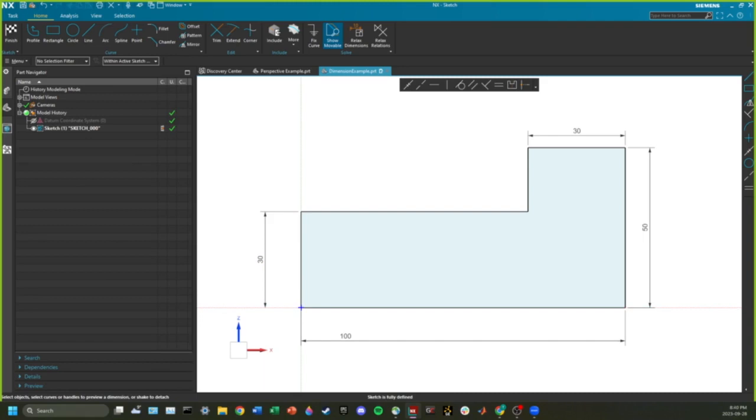In manufacturing, this is good because imagine you had one true edge or one true corner, and you know that everything from this edge outward is where I want to be. And you start machining things and you start taking metal off, but you know that this corner is going to stay the same no matter what. That is what drawing up dimensions from an origin is. If I said, okay, I want you to machine 100 this way, 50 this way, and then 30 over here, that 30 is still a dimension, and on a model it's correct.